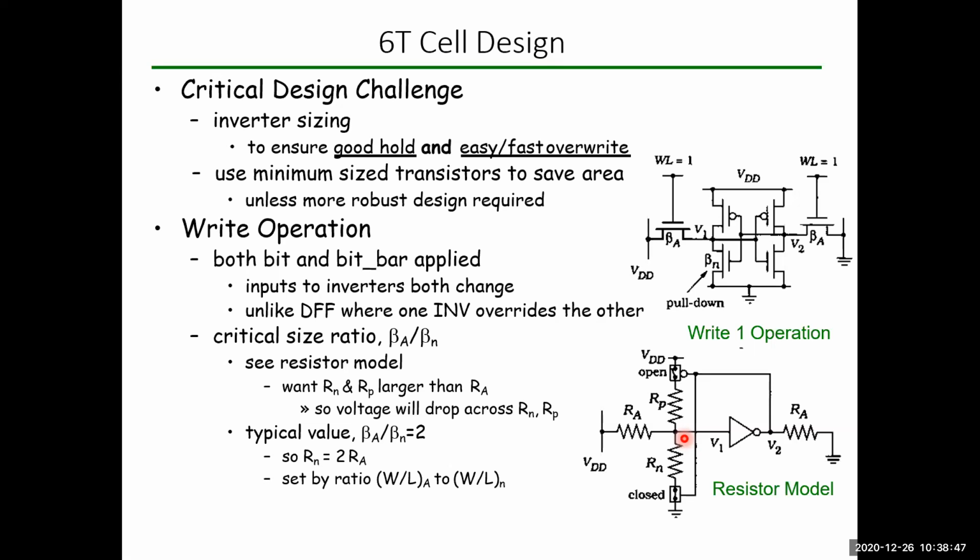Whenever the path between the bit line and latch is disconnected, the data will be held. Whenever a path has been created between a bit line and a latch, then a read or write operation happens. The same thing happens here. We are just trying to represent the entire SRAM cell in a resistive model. That's the only difference. The entire operation will be the same. Is it clear? Yes, sir.